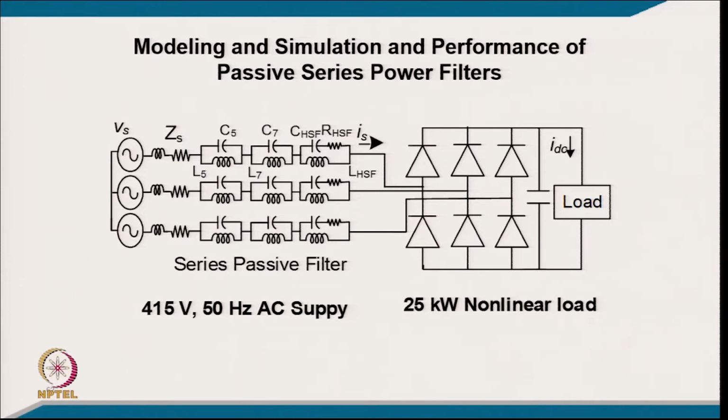Now, earlier only 2 diodes were conducting at a time, because out of 3 diodes, 2 conduct, and sometimes none of the diodes are conducting. Out of 120 degrees only 2 diodes should conduct at a time, but because of discontinuous current, you will find even none of the diodes is conducting, and the capacitor is feeding the load, depending on the value of the capacitor and the equivalent load resistance or time constant. But now you are forcing all the diodes to conduct, and only then are these currents becoming sinusoidal. So, all 3 phases are conducting and you are forcing.